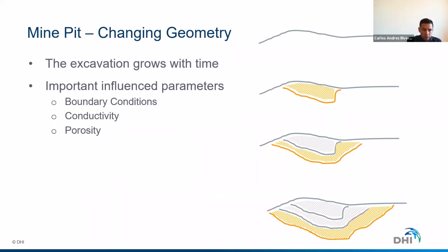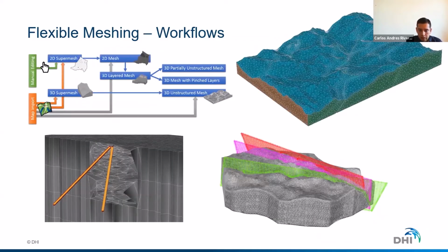For those working with MODFLOW, the concept here is a little bit different. We don't do a deactivation to solve the unsaturated flow. We basically deactivate the elements because we want to represent changes of the geometry, excavation, advance of mining plans, advance of tunneling, etc. And nicely, you can change properties of boundary conditions in parallel with these geometrical changes.